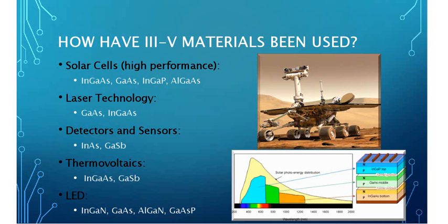So how have these III-V materials been used in the past? Typically, one suggestion is solar cells. In this case, you have III-V materials being used quite a bit. One example would be a single junction cell of gallium arsenide reaching roughly 25.8% efficiency back in August of 2008. Today we have more complex structures, such as this one I depict over here, which have found their way onto space exploration, which were used on this robot, which is Spirit, used to scale Mars and to look around.